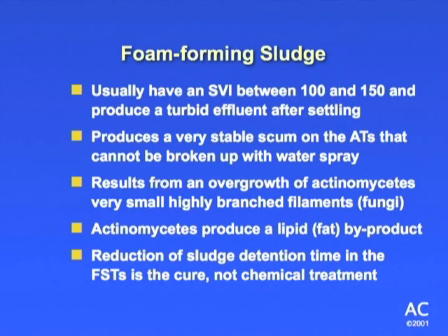And again, you've got options there too, because if you get a high storm event, and you're not going to overload the plant hydraulically, you now have your option, and you will be doing it too, of course, to take what the plant's designed to take flow-wise and divert excess through wet weather discharge. So this is all trying to tighten up how the package is being run, so to say.